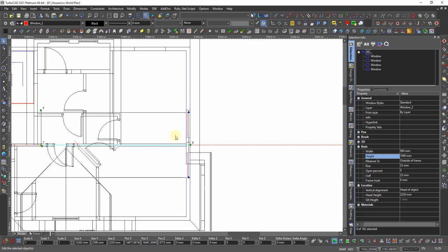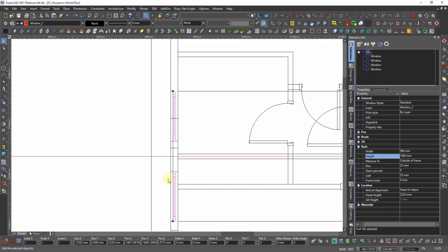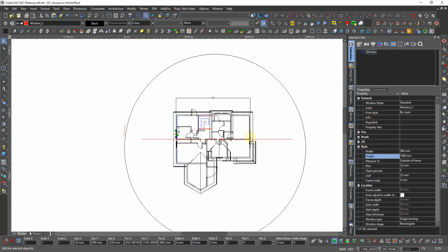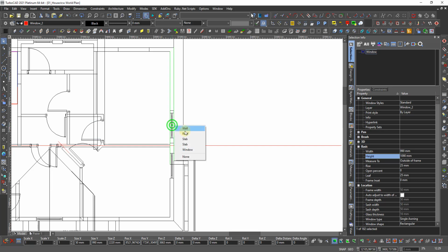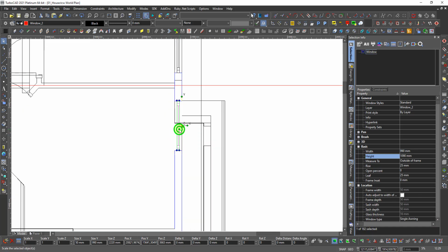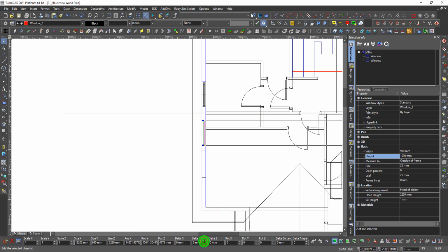Then we have this, but now there's also a bigger distance there, so we can take them back again. I take that window and that window, and I move it down, delta y minus 50, half the dimension, we change it 10 centimeter, and then I take this, pressing shift, and take this, and that I'm moving up 50.